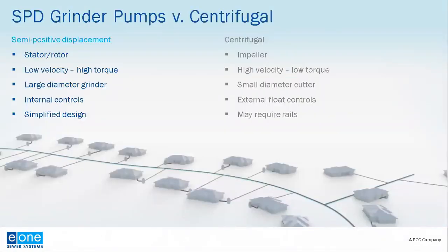So, a little bit of a comparison between semi-positive displacement grinder pumps and centrifugal pumps. With an SPD pump, you're going to have a stator and a rotor, and that's based on the Moineau principle. It goes back several hundred years, and really it is a sequence of chambers that progresses and physically pushes water out of a discharge location, as opposed to a centrifugal, which creates a vortex and allows a discharge location.